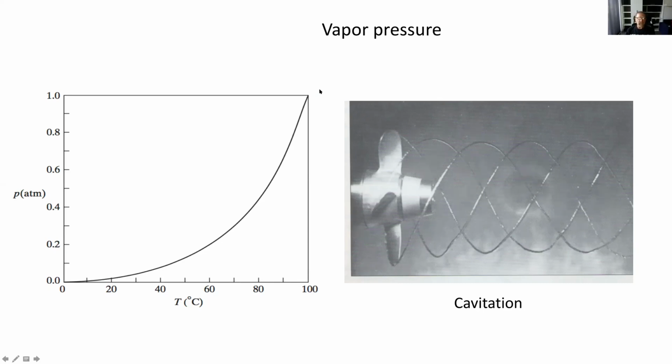Again, we're not going to speak about temperature changes, but let's just see why it is so important. I want to cool your engine, your car, with water. And I would love to have temperatures higher. I don't want it to boil at 100 degrees. So one option is to change the pressure. Say I want to go further up, I have to change the pressure. So if the pressure inside the system is, say, 2 atmospheres, then I can go up to a higher temperature where I can actually continue. It's probably 120 degrees. Okay.